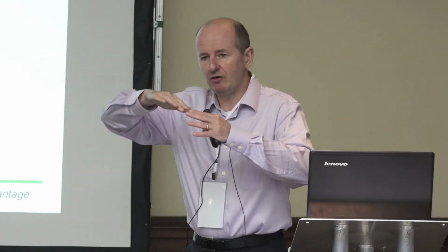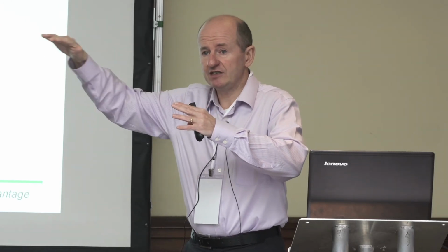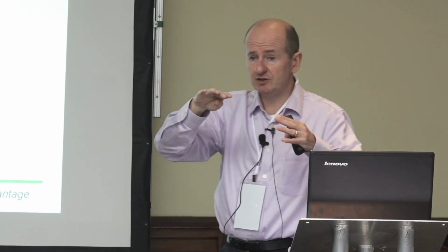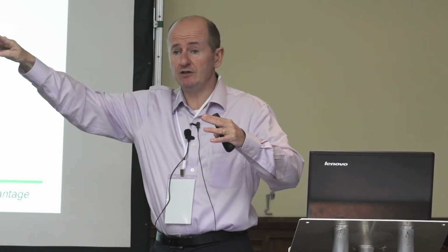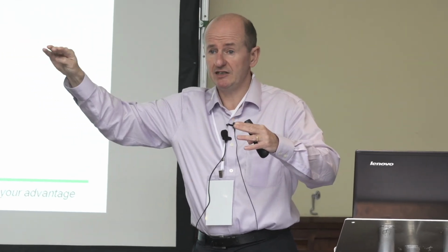If you imagine you've got this soft compression characteristic that goes on for a long time, and then you've got the same on the input stage, but you've sized it too small. So it starts compressing here, and it goes on forever. And really, you can buy commercially available parts which require you to drive them 10 dB into saturation to meet the advertised PSAT. Can you tell me the amount of gate current you were expecting?